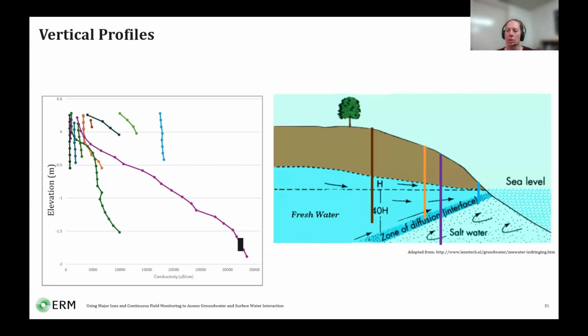So why is there such a variation in EC at depth? Just before we move on to that, in that sort of scenario, you can use manual meters. Solinst make one, an LTC, which you just lower down on a tape and you can read off the EC on the side of the reel. It's often hard just using a data logger, lowering it down, bringing it up, downloading, working out the location, but you can pretty much effectively work out your best location on the fly using one of those meters.